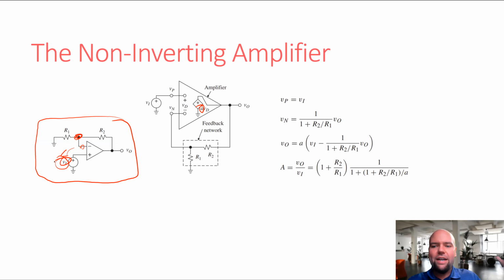That's, I said I'm not going to go over the basics, and I'm kind of quickly going over the basics. So let's start building our equations for this. Ideal analysis, we would just assume that the voltage of the negative terminal was V in, and then we could immediately start finding currents and voltages and finding our solution, but we can't quite jump there right now. So in this case, we still can assume that the voltage of the positive terminal is V in because it's connected directly to it, and because we're still assuming that the input resistance is infinite. So we can say the voltage of the positive terminal is V in.